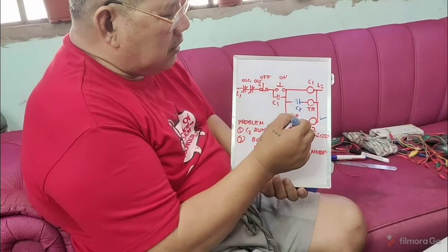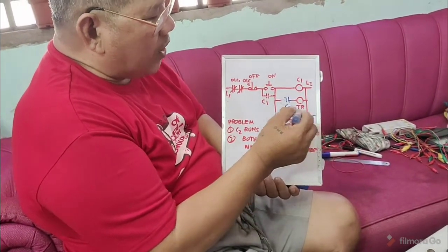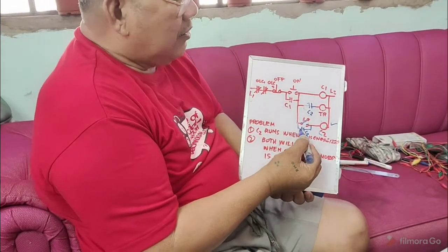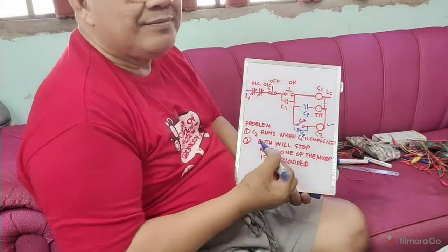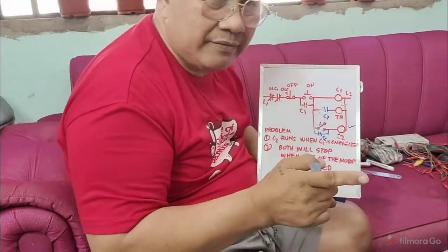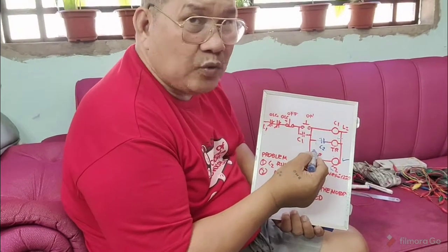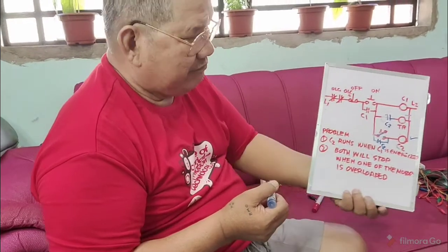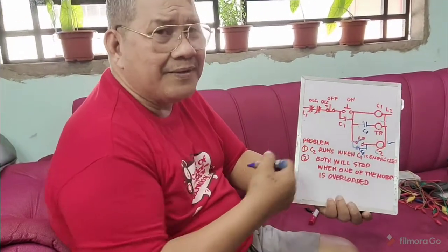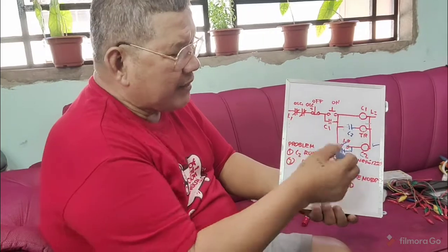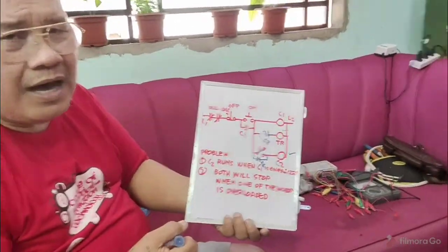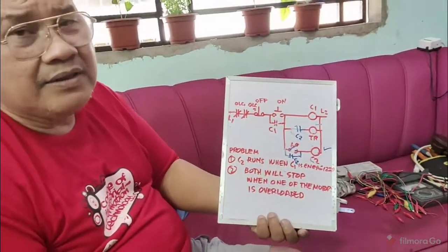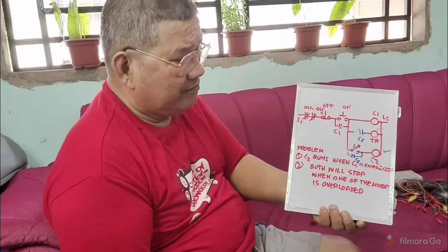But the motor now, the conveyor 2 now is running because of the maintaining contact. Okay? So you preserve this one. But remember, the number 1 is already correct. But for me, I prepared this one so that I can preserve the life of the time delay relay. That is it. The same condition will happen. Okay? The same, but another way of making a diagram by preserving the time delay relay.